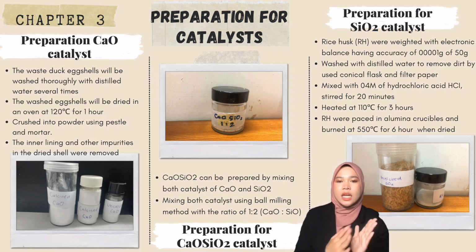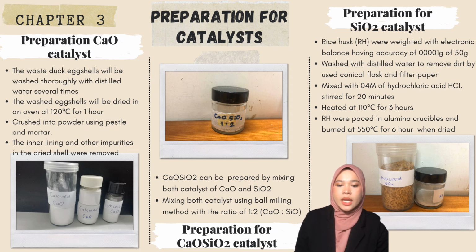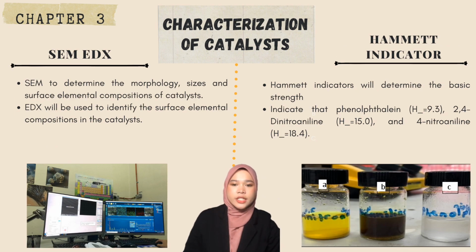Next, for the mixing of CHARACTERIZATION, mix both catalysts using ball milling method with the ratio 1:2. Okay, for the characterization of the catalyst, SEM-EDX. SEM is used to determine the morphology, size, and surface element composition of catalyst. EDX will be used to identify the surface elemental composition in the catalyst.